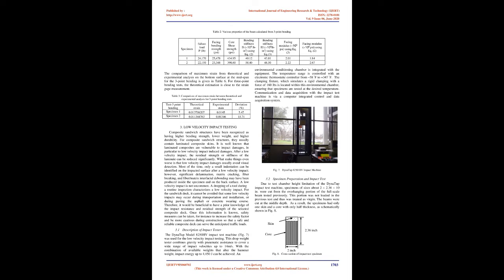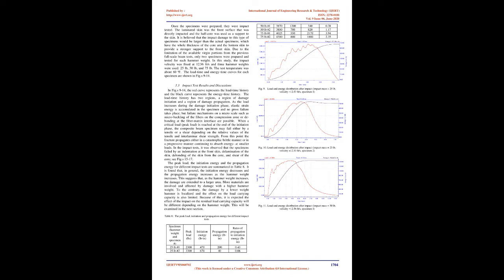The LVDT is connected to a data acquisition unit which gives the instantaneous displacement of the beam. The strain gauges are placed at different locations, middle top, middle bottom, and middle side face, of the beam to measure the local strain of the beam. Load versus deflection plots are generated and analyzed to find the flexural properties of the beams. 2.3 Testing results. 2.3.1 3-point bending test results. 3-point bending test loading configuration is shown in Fig. 4. 2 specimens were tested under 3-point bending and the load versus deflection graphs for those tests are shown in Figs. 5 and 6. The first part of the graph in Fig.